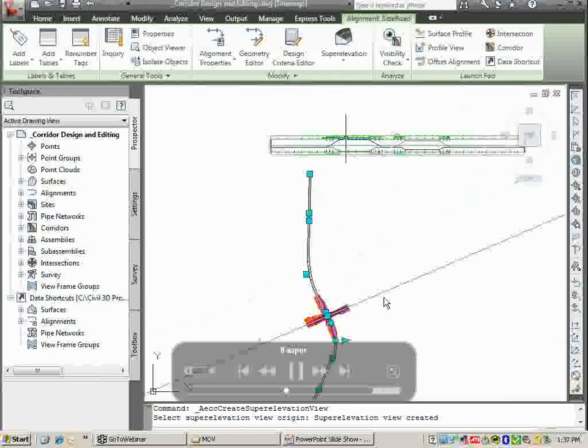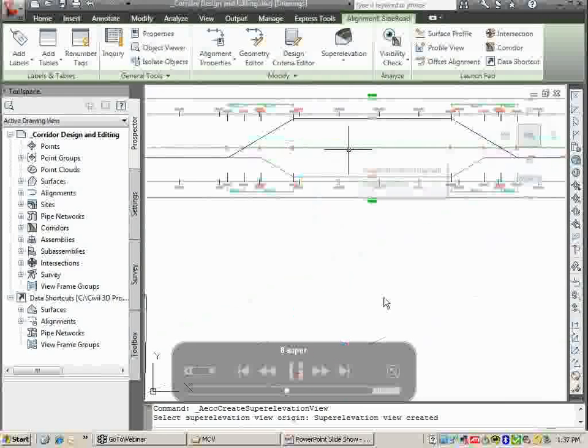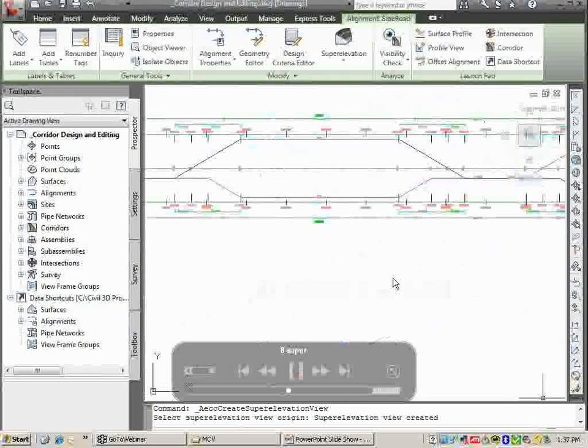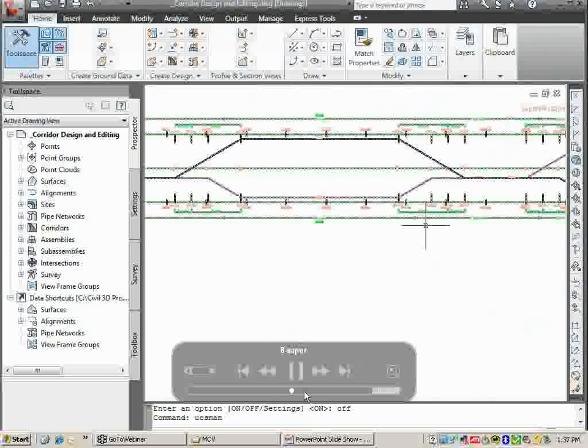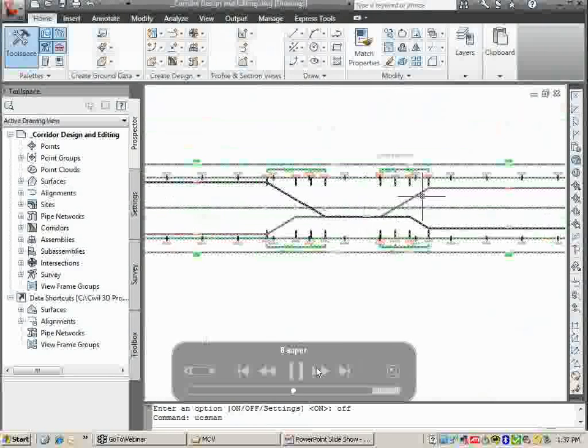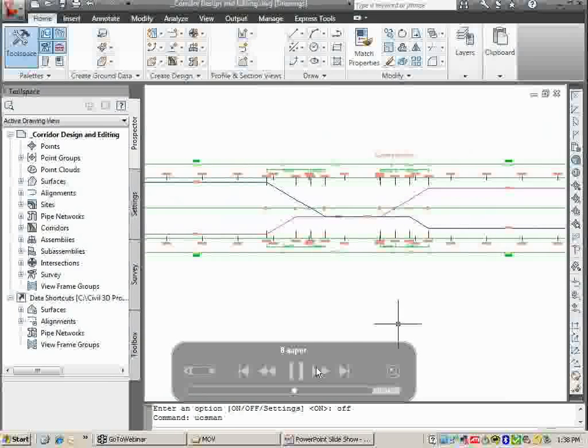And in a moment you'll see it here. This is a band diagram, but with a super elevation left and right in it. And this super information has what are called grips in it, and this is where we're tied straight to AutoCAD. Now we can come in here, tag this thing, grab a grip and do edits to our super. These edits will reflect back in our tabular data, as well as go straight to our road and affect the way the roadway interprets super.